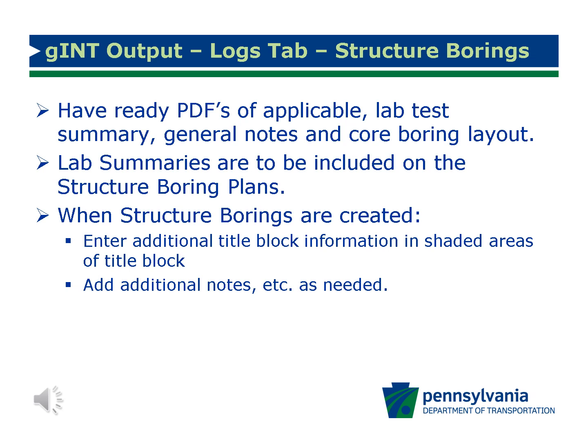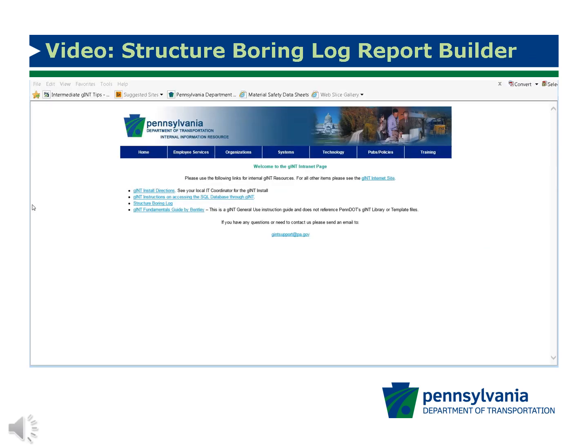The appropriate general notes output reports and core boring layout should also be in PDF format. General notes are produced using the Graphic Table tab and will be discussed later. Please click on the screen and then on play to view a video demonstrating the use of the Structure Boring Log Report Builder. Note that only PennDOT personnel currently have the ability to use the Structure Boring Log Report Builder.